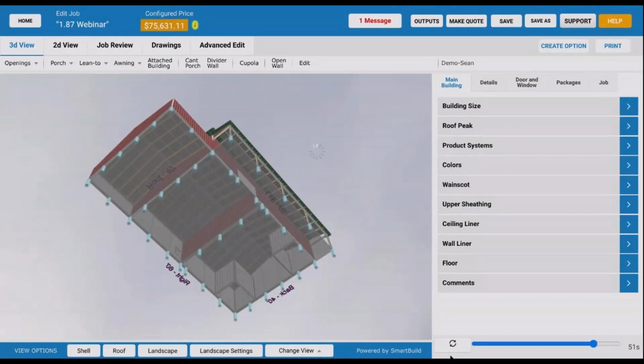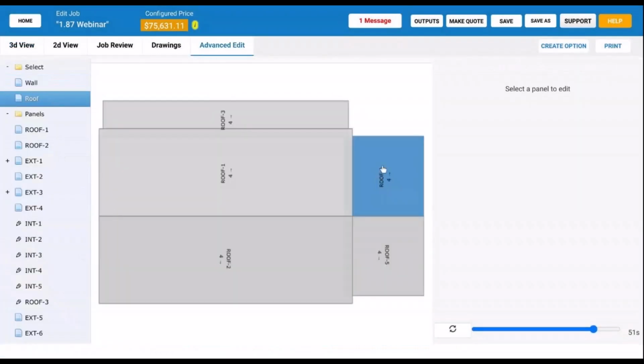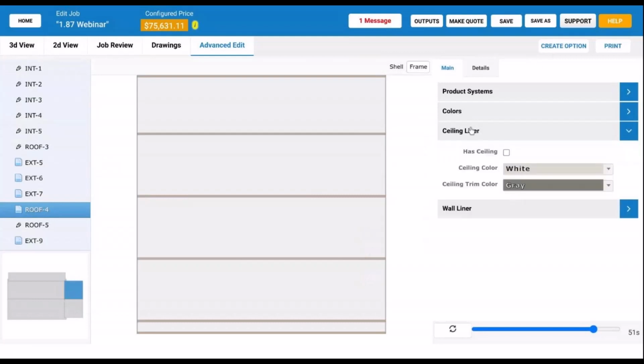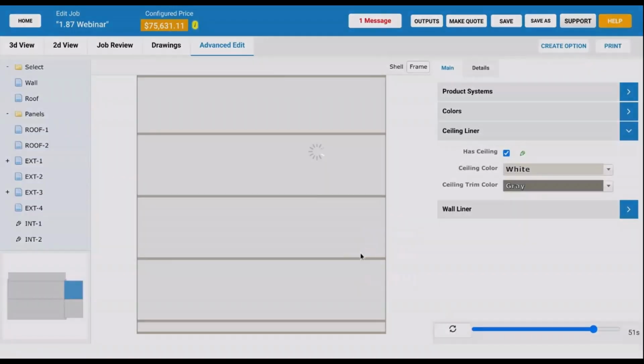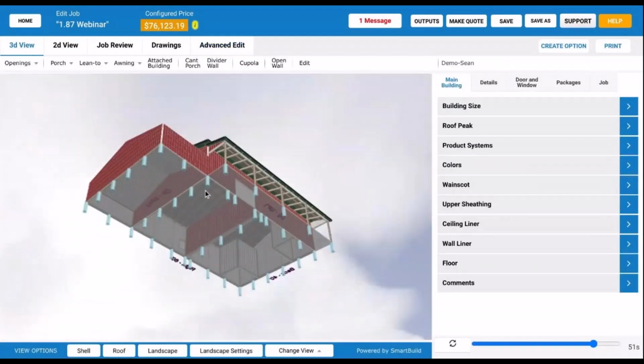So what I noticed is specifically what I'm looking at is if the building is all the same height and I do the attached building, like the roof properties and everything are the same, it will combine the finishes from both sides and it'll make it one roof. So it takes away the control. Yep. From the attached building side. Yep. That's a great point. Even if I have the don't combine walls on, yeah, it'll still combine the roof. Yep. Doesn't help you with the roof.